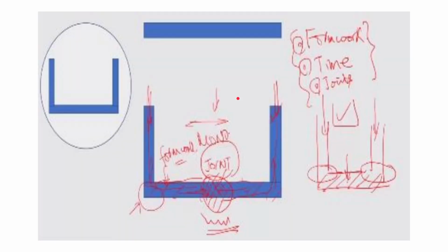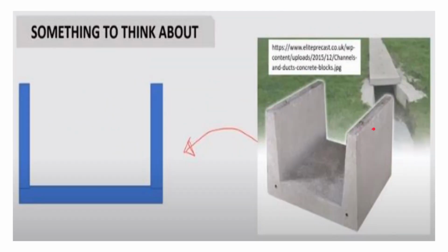So basically the use will result in less requirement of workmanship and skilled labor, okay. And secondly, we can adjust this by properly making the forms in the lab itself. We can increase the volume of water that can be collected through the precast drains, and this will also reduce the weight of the precast drains, okay. So it is having two utilities. If the upper size is reduced as compared to the lower size, the weight is reduced. And apart from that, a larger amount of water can be passed through.